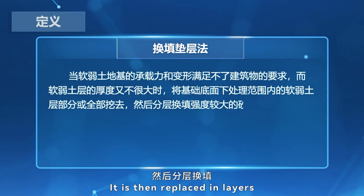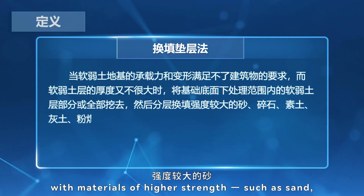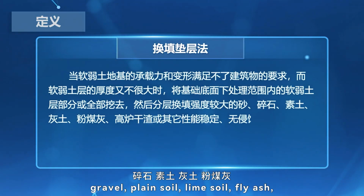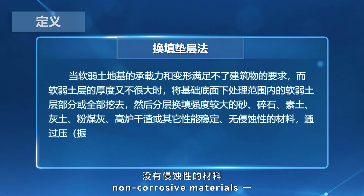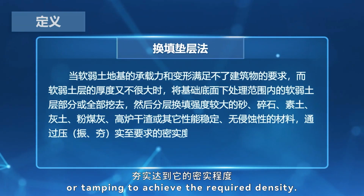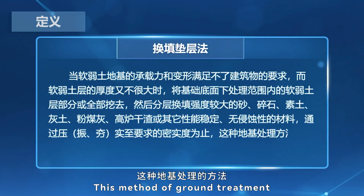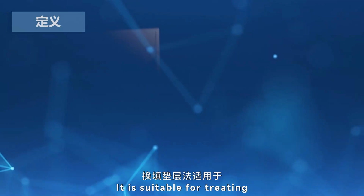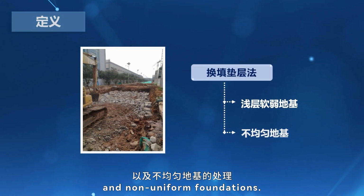It is then replaced in layers with materials of higher strength such as sand, gravel, plain soil, lime soil, fly ash, blast furnace slag, or other stable, non-corrosive materials, followed by compaction, vibration, or tamping to achieve the required density. This method of ground treatment is called the replacement fill cushion method. It is suitable for treating shallow weak foundations and non-uniform foundations.